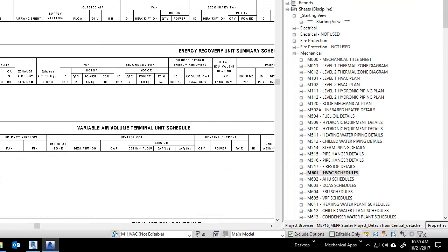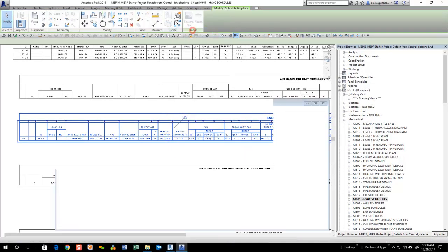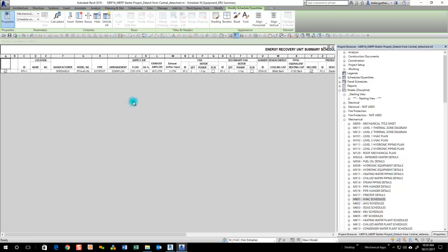In this video, we'll be talking about another one of the design schedules, which is equipment airflow. So the families in the MPP have been set up to use connected airflows with the ability to override that information. In doing that, what you end up with in the schedule is a calculated value that you can't edit. There needs to be another way to edit these values.